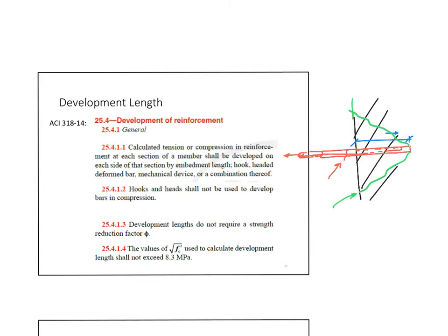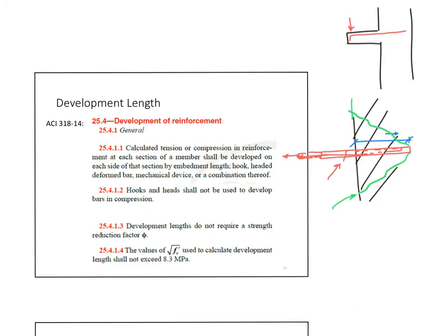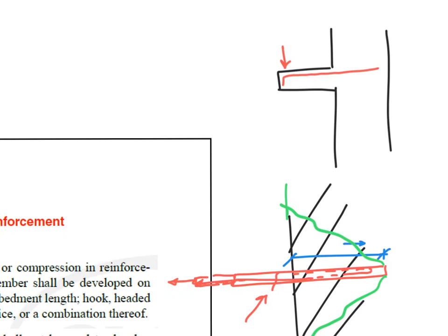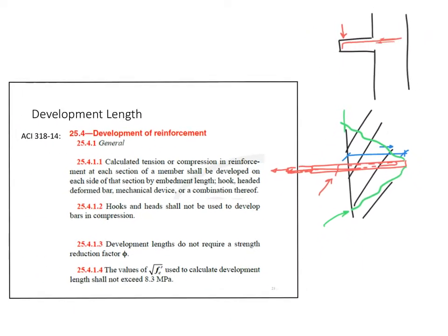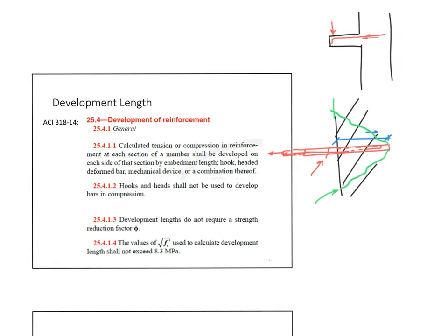So this is exactly what happens. You would have a beam like this, and that beam sticks out of a column. Let's imagine this is the column, this is the beam. I have the perfect amount of reinforcement to take my load, right? Everything looks good, but then at the end, instead of breaking the beam or crushing the concrete, you slipped out here, and this bar got out of the concrete. This is really, really unacceptable. So for this reason, they came into the code and decided to put provisions for development length, Ld.